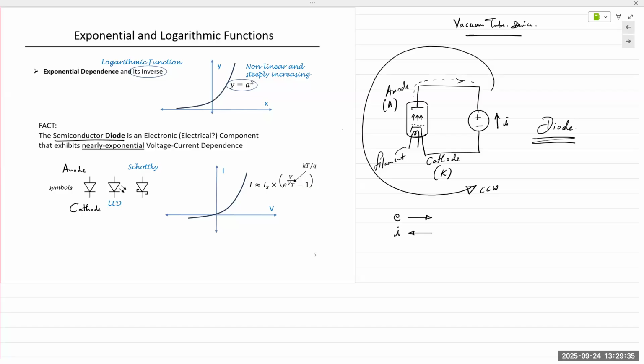Okay, coming back to our topic. The reason we're talking about the diode is it's the most fundamental of semiconductor devices. The relationship between the voltage and current for a diode is not linear. For a resistor, we say the relationship is linear. For a resistor, capacitor, or inductor, the relationship between the voltage and the current is linear. As voltage increases, current increases; if it decreases, current decreases. But for a diode and a transistor, FET, BJTs, the relationship is non-linear.